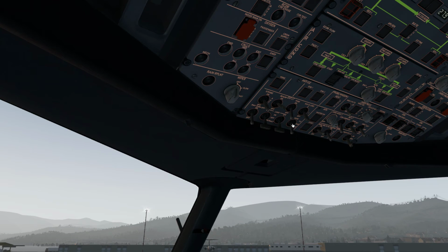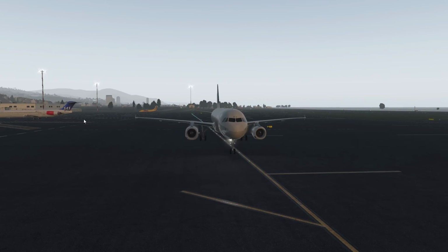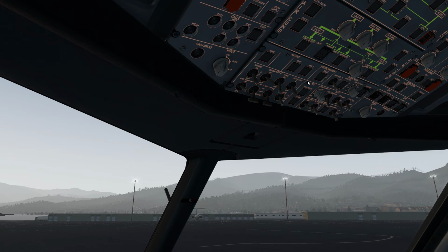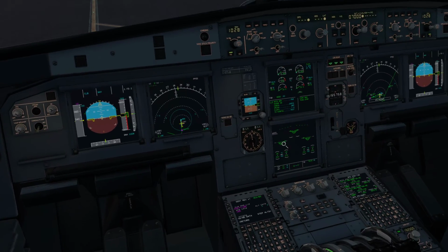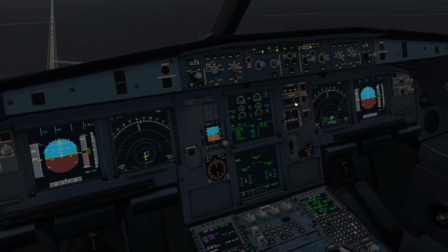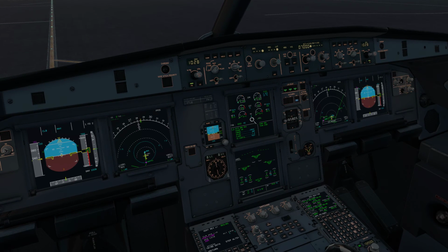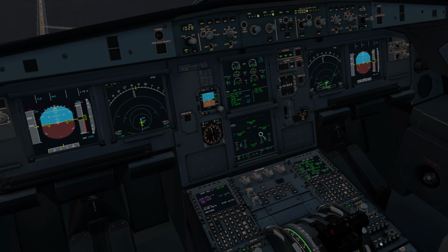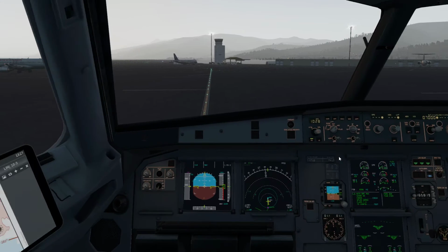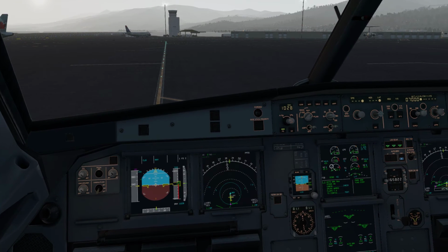So, what's up next? We're going to turn on the taxi light. This is the ECAS. It'll tell us what we need to do before taking off. So, before taxiing, we actually put auto brake on max. Arm the spoiler. Put the flaps to takeoff, which is 1. They go down here. And yeah, for taxiing that's enough.